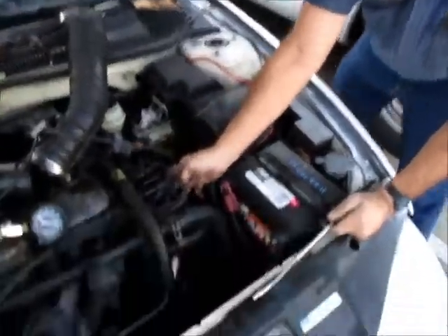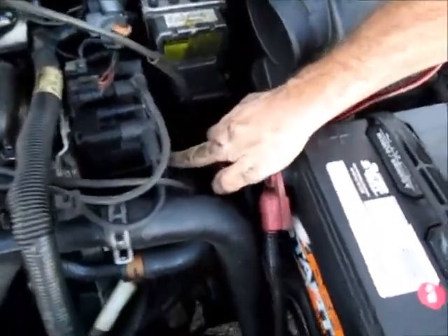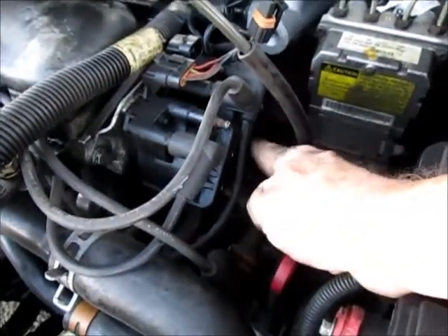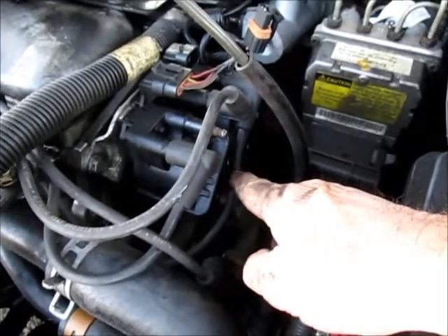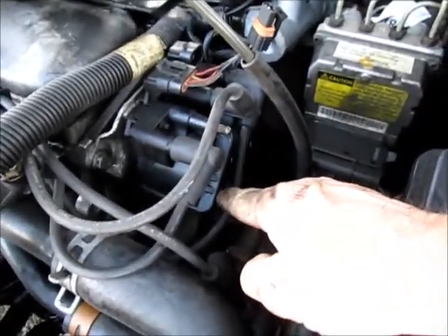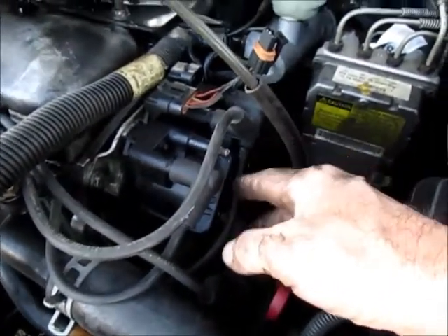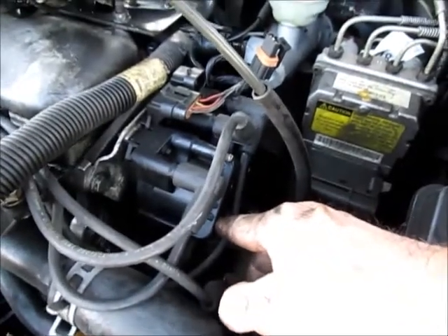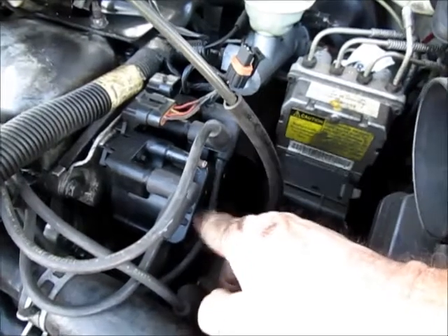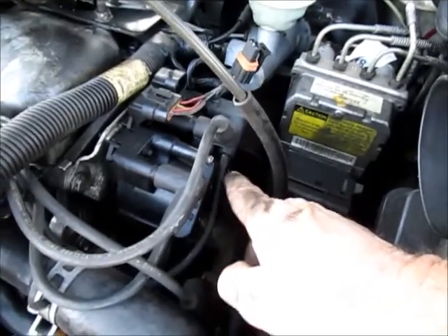Swap these two. These are called waste spark coils. The way this works, if you can see the numbers, number 1 and 4 are companion cylinders, and number 2 and 3. What that means is that on the compression stroke, when the 1 fires, it also fires the number 4 cylinder, which is on the exhaust stroke. The reason they did that was as an emissions reducing method, to fire the mixture if there's any left in the cylinder during the scavenging out of the exhaust, to help emissions. Anyway, that's the way it works.